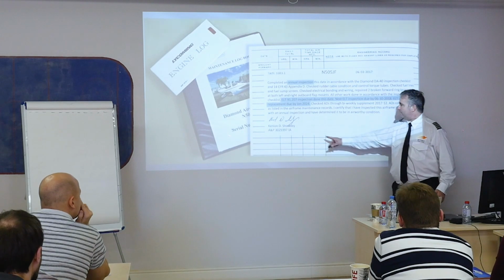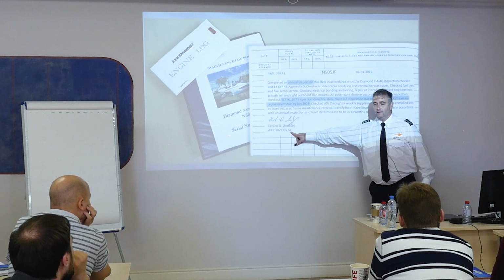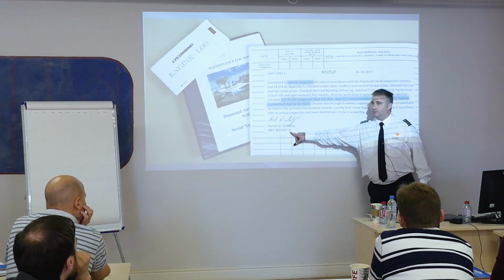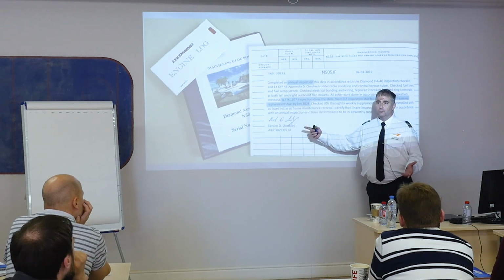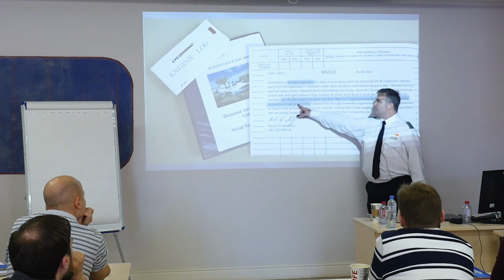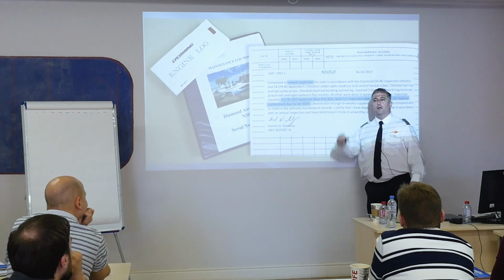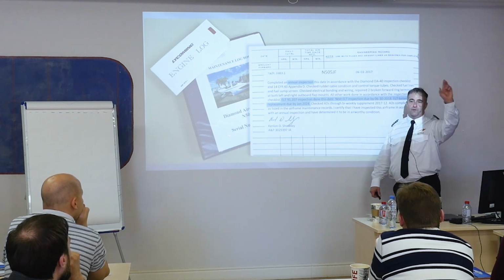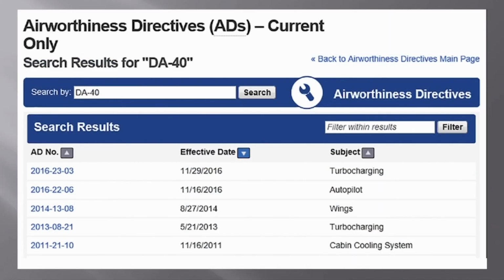It's an inspection. Take a look at this. IA, Inspector of Airplanes. Okay? If it doesn't say IA, then that person is not an inspector, right? They can't do an annual inspection. So if I'm looking for annual inspection, I'm taking a look here. Then it usually says ELT on the same day because those are done every 12 calendar months. Now, the only one caveat, the only one exception that we had for that airworthiness certificate to be valid is right here. Airworthiness directives. The airplane has to remain in compliance with any and all airworthiness directives.